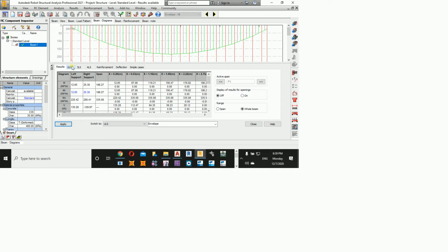You'll design it for something more, as you might assume that your weight might be increasing, or somebody else will be sitting. So for example, instead of 100, you will design it for a 1.4 factor of safety, so 140 rather than 100. You have designed it for 140. So it means that you are designing for an ultimate load of 140. So that's the ultimate limit state, whenever we are taking into account the design or bending.